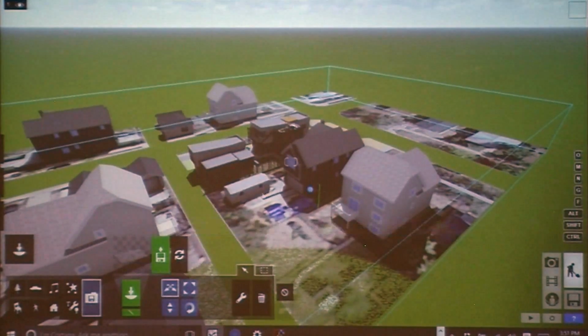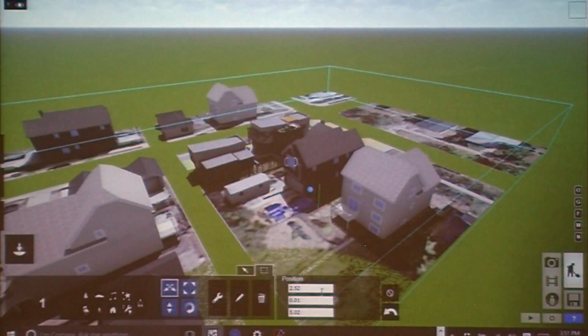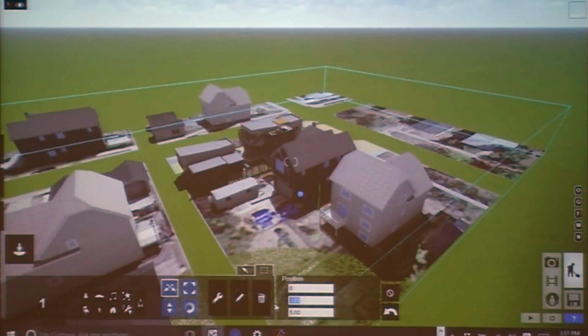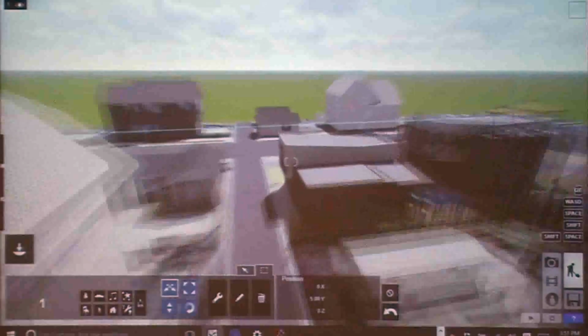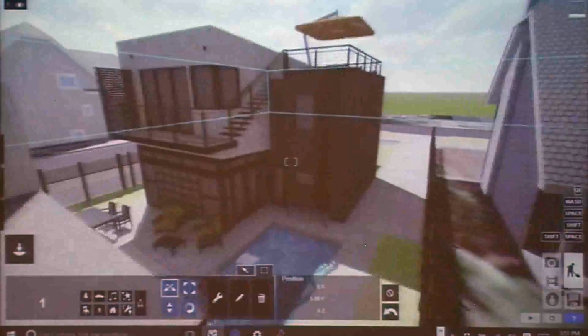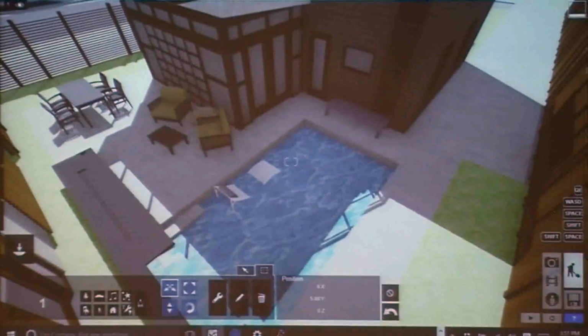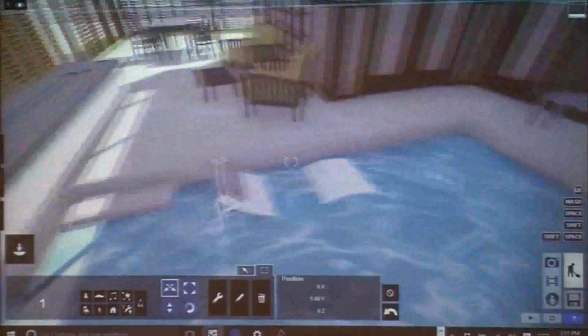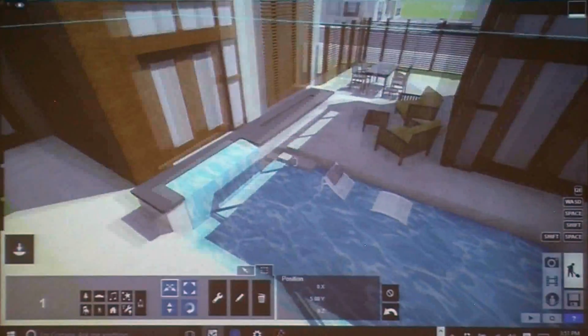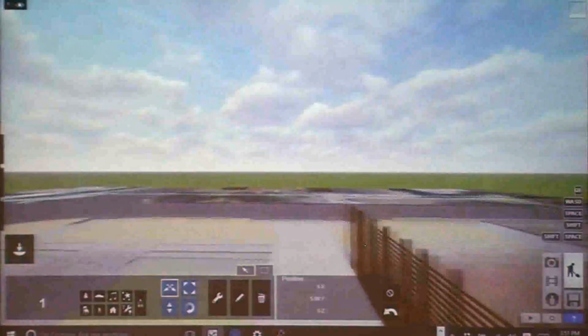So now I can go to my Move tool, Move Mode, and go with, I always do 050. That way everything can be imported again, and if I need to stack different SketchUp models on top of this, I have an origin point. But check it out, our main materials that really shine in Lumion are glass, grass, and water. So let's talk about glass and grass first.